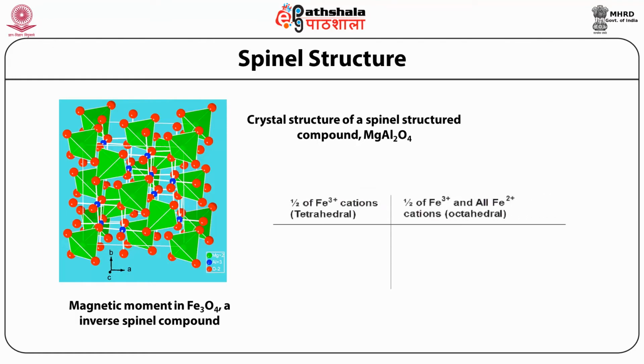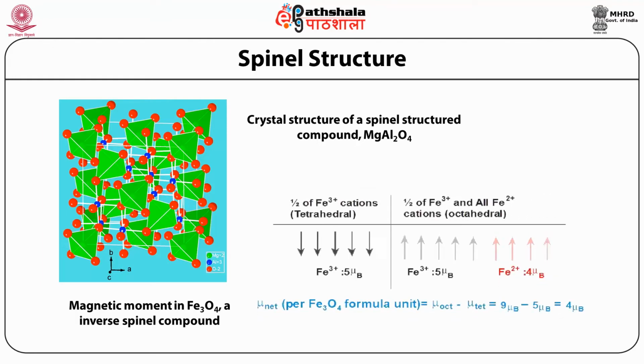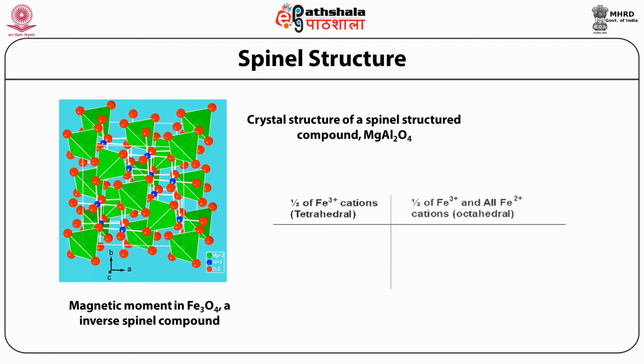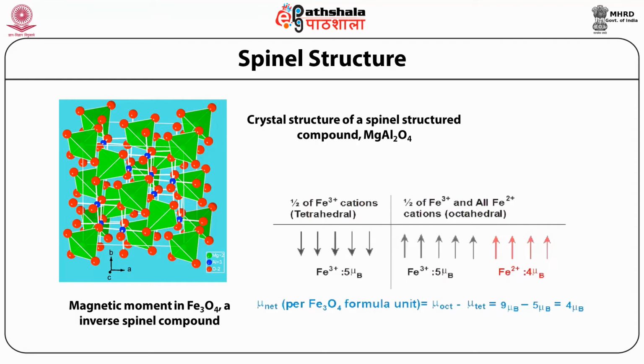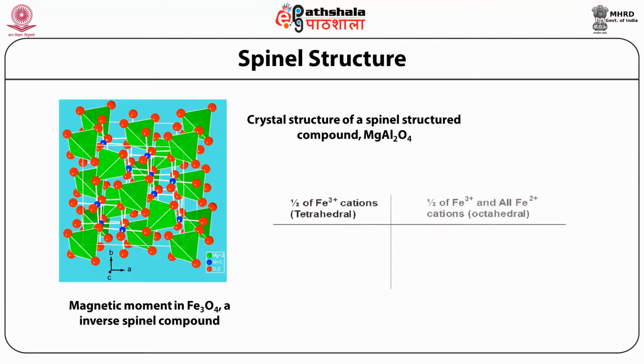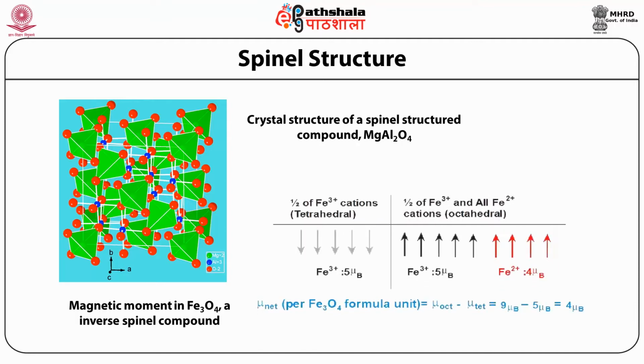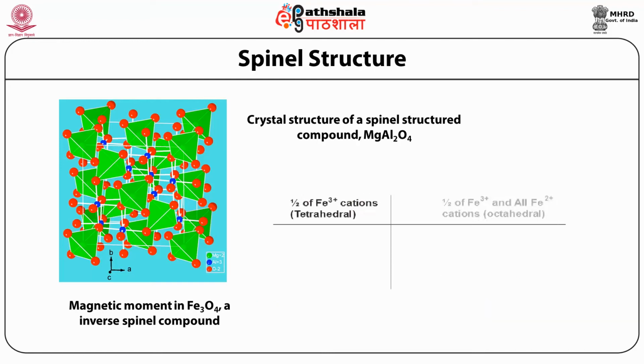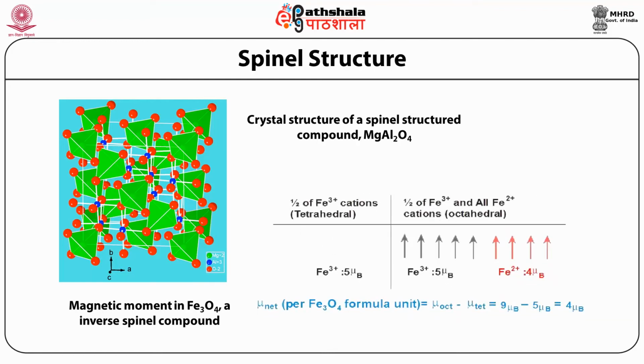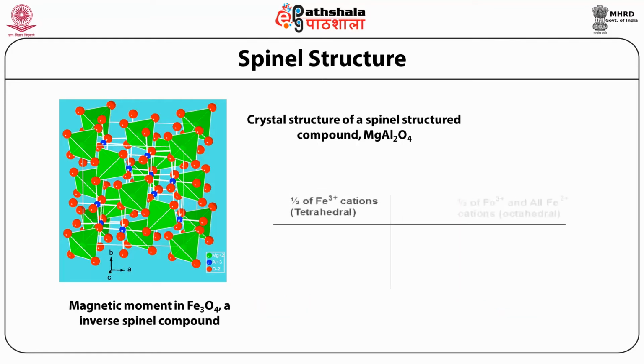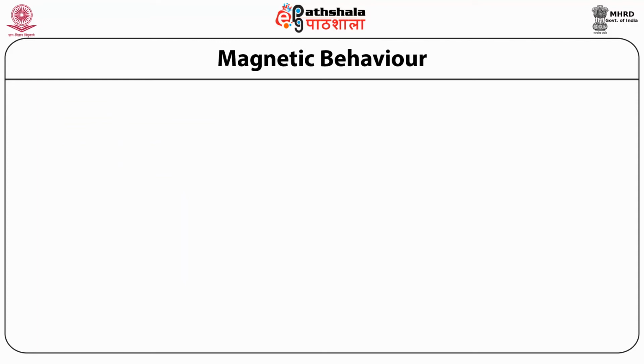One can tune the magnetic moment and Curie temperature of spinels by preparing a solution of two spinel compounds that are miscible into each other, such as a mixture of zinc ferrite and nickel ferrite. In general, cubic spinel ferrites possess low magnetic anisotropy and are soft magnets. So as we have discussed in the previous slide, the magnetic behavior.